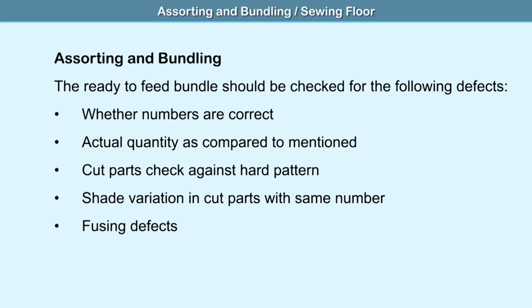Assorting and bundling. The ready to feed bundle should be checked for the defects, whether numbers are correct, actual quantity as compared to mentioned, cut parts check against hard pattern, shade variation in cut parts with same number, fusing defects, etc.